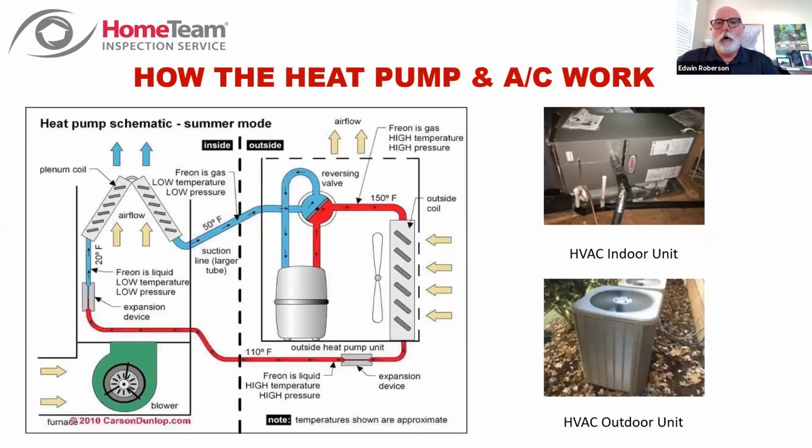So when we talk about heat pumps, you really are doing nothing more than adding a reversing valve that simply reverses the flow of the refrigerant. So you reverse the tasks of the two coils. In this particular case, this is configured the same as what you saw with the air conditioner, in that this is in air conditioning mode now. So your indoor coil is cold and your outdoor coil is hot.